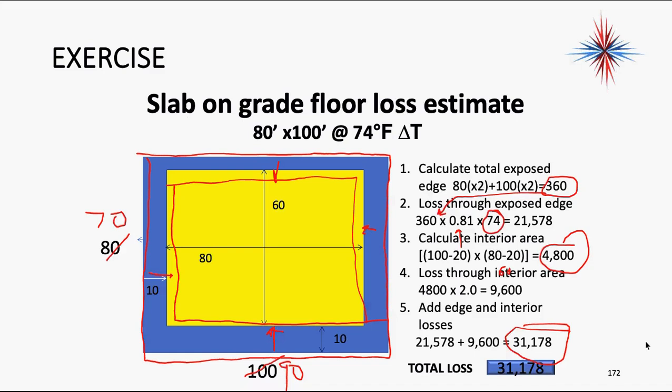So if your house or a customer's house you're looking at has a 100,000 BTU furnace installed and they all of a sudden want to add ductwork to the basement, and let's say the rest of the house is sized about 90,000 or 95,000 BTUs, and they want to add ductwork to heat and cool their basement, will it work?